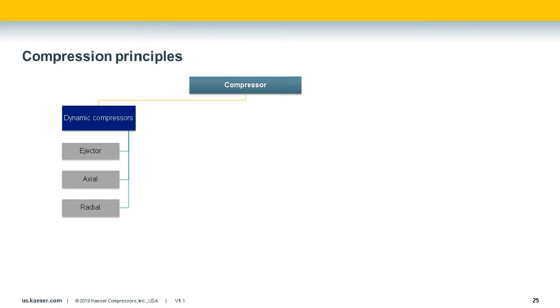So we've talked about the applications of the blowers and how they work together, but let's get into a little bit more about blowers themselves, and maybe this might also provide some additional insight as to why we are seeing those numbers vary like we did. So within the blower market, the first one we're going to talk about are dynamic machines. Dynamic machines work by accelerating the inlet air in an axial or radial direction. For blowers, this is typically radial. Examples are multi-stage centrifugals, turbo compressors, and most recently, high-speed turbos.